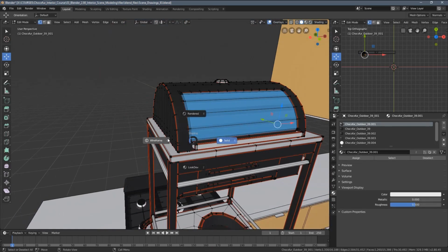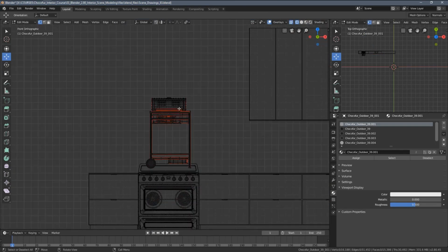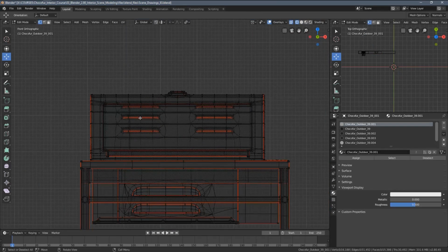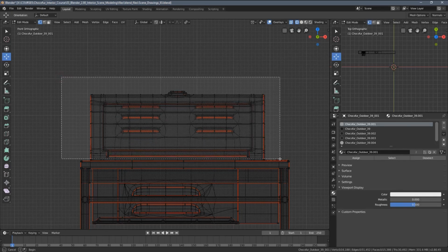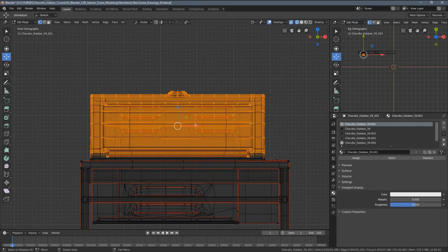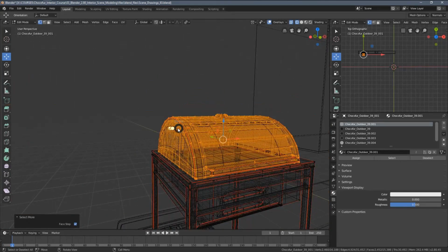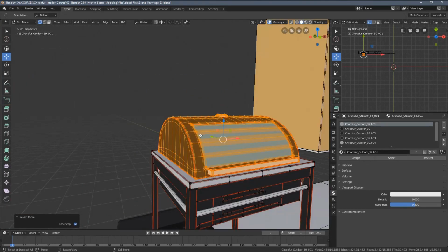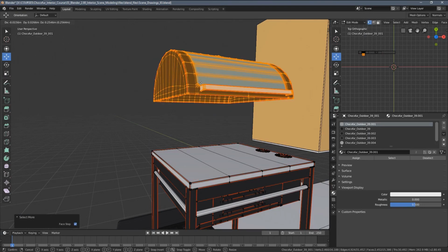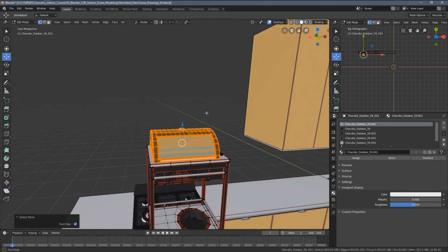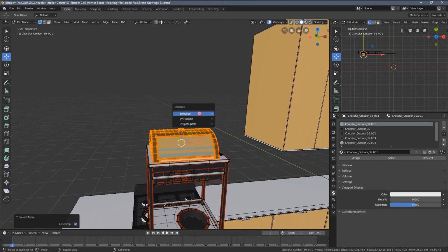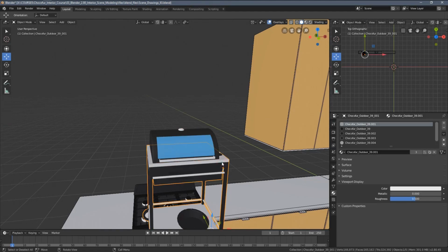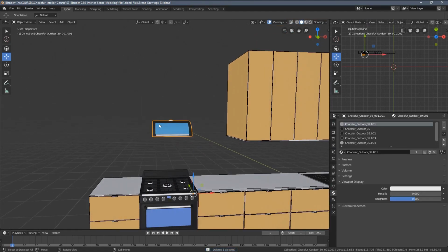And now in the edit mode, I could do this both ways, maybe just selecting everything from the side view and now holding my control key and pressing numpad plus, I'm just maxing out the selection, so I know all of the vertices from the upper part are now selected. Yeah, so I just press P, separate selection, delete this bottom part.